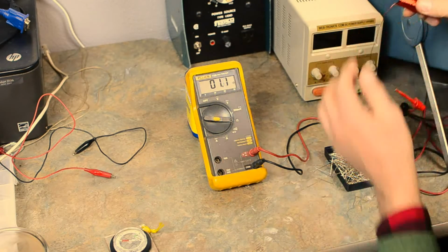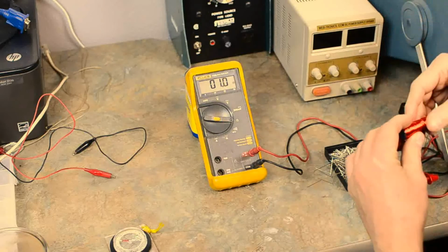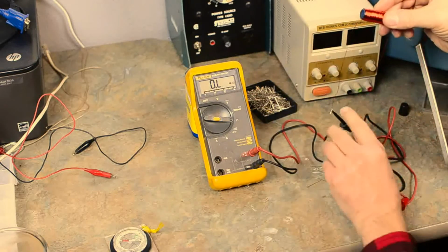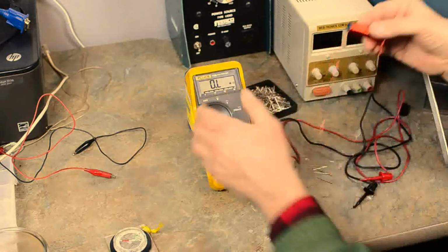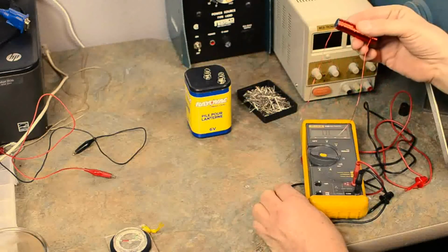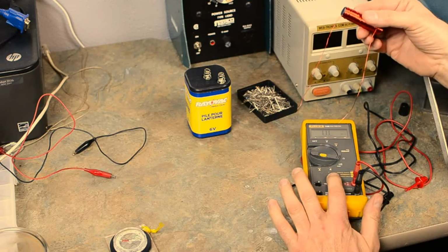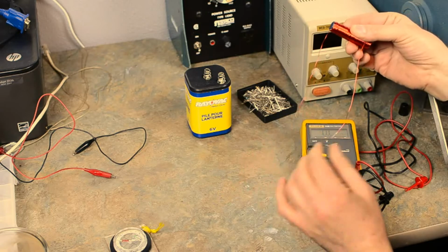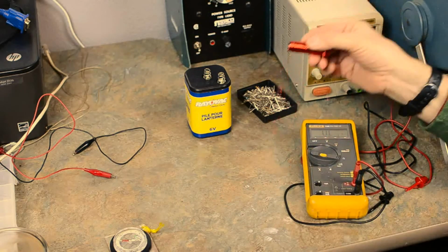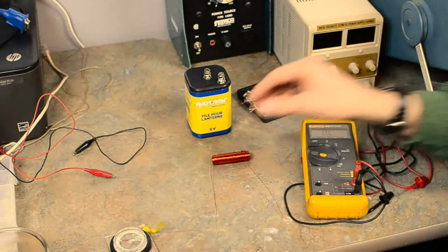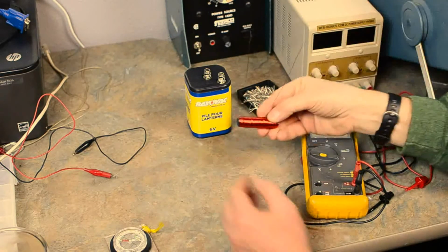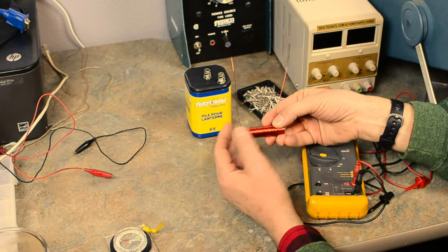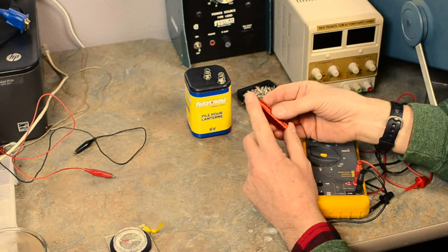This is wire. It's thin wire, so it does produce some resistance. But from our Ohm's law lesson, we know that we have 6 volts from our battery, and we have 1 ohm of resistance. To calculate the current, I equals E over R, or volts over ohms. So if I take my 6 volts and I divide it by my 1 ohm, that's going to be 6 amps. So this little 24 gauge wire had 6 amps running through it. It doesn't take long for this to get quite warm.